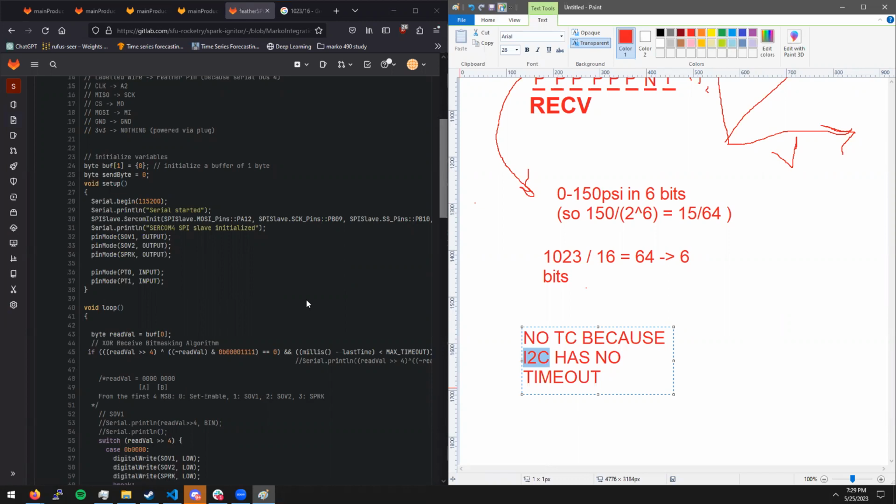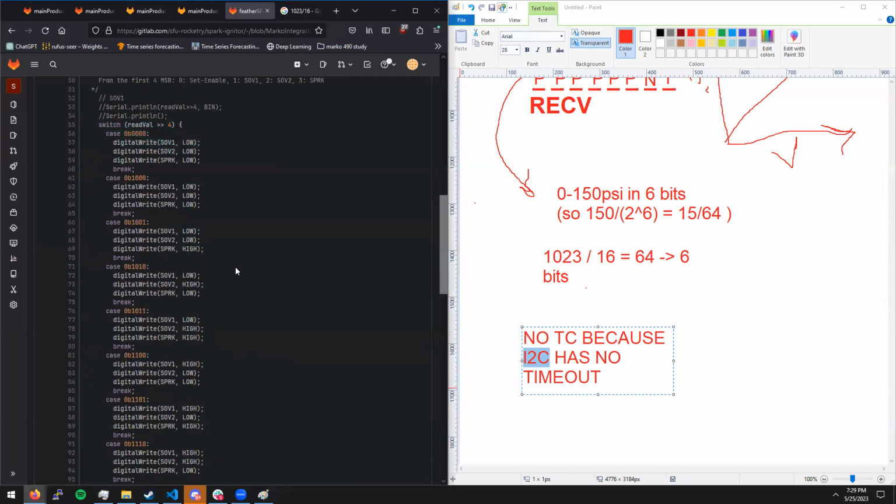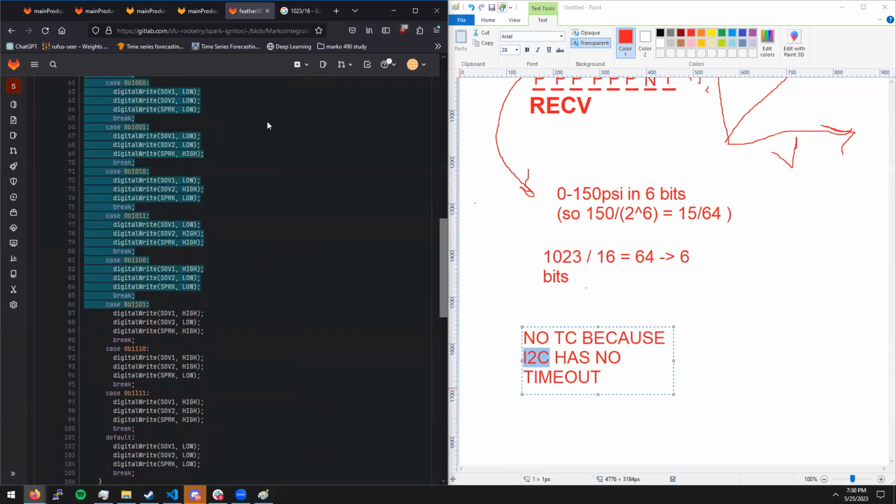Because how it works is when you try to do an I2C message, you send it, and if you want to receive a message, you sit there and you wait infinitely, and you can't do anything else while it's doing that, or at least not in a simple linear program. It'll block sitting there waiting until it receives the proper ACK acknowledgement ping. So there was a situation where I'd booted up, and if the thermocouple wasn't working right away, then it would freeze the entire program. And I didn't want to take that risk, so I just removed it.